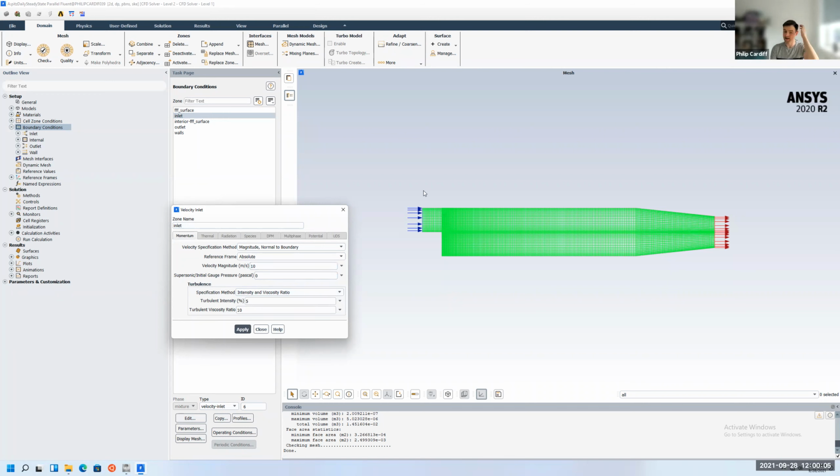So we're not going to have a parabolic profile because there wasn't a parabolic profile, and it was an incoming turbulent flow. So for the true experiment, you can find the original paper, and it's a much bigger system. This is just the experimental chamber, so you could model the full system. But basically, the average velocity was 10 meters per second coming in here, and the boundary layers were very, very thin, so we're not going to prescribe those.